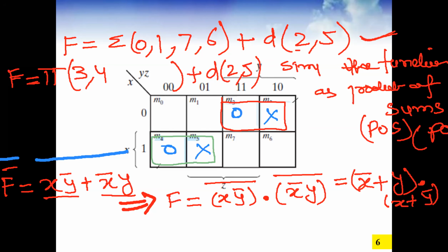Okay. So this is about 3-variable K-maps with don't care conditions, and even if you want the solution in product of sums, we can do this. Provided, keep in mind one thing, don't cares are going to be the same. Don't care cannot be minterms and maxterms. So the don't care which is given for the minterms is going to be the same for the maxterms, basically. Right?